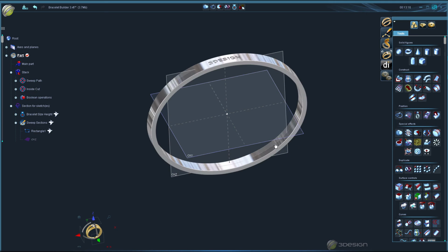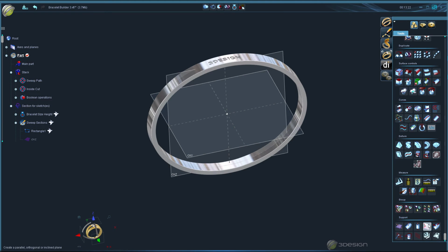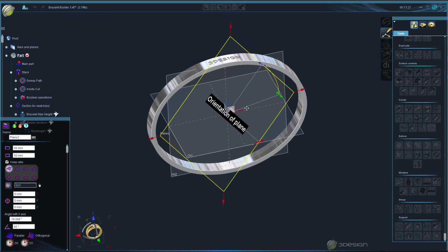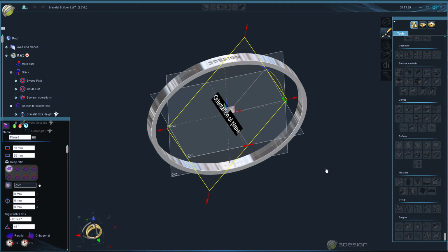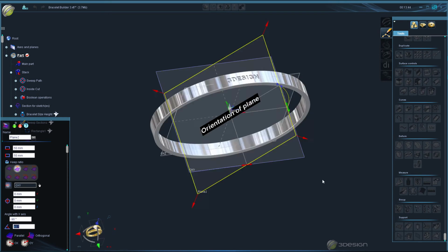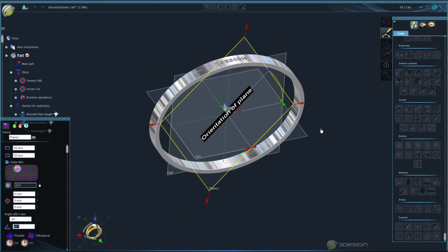And I want to do that from an angle. I want to put the year inside this lower right corner. So we're going to do another plane based on the default OXY plane, only this time we need to turn it. We'll leave it 45 degrees so that it's going towards the corner. We need to turn it facing the right corner. That looks to be -90 for the X angle. Perfect. Now we just need to change our orientation, and that looks to be a 90-degree turn. And yes, that's going the way we want.